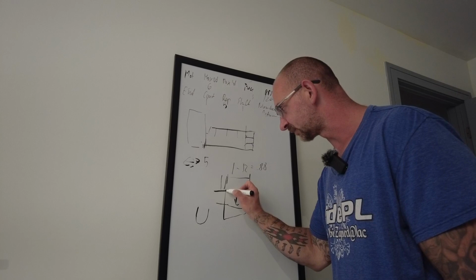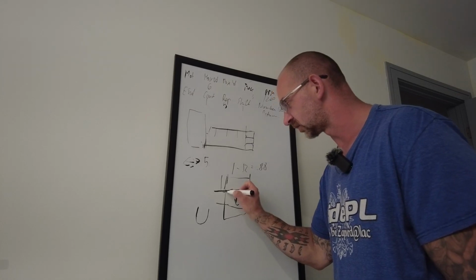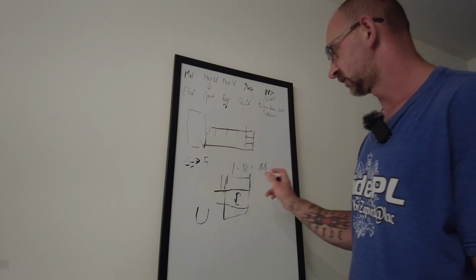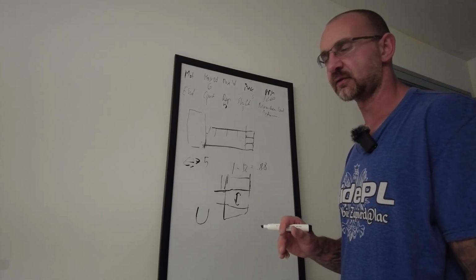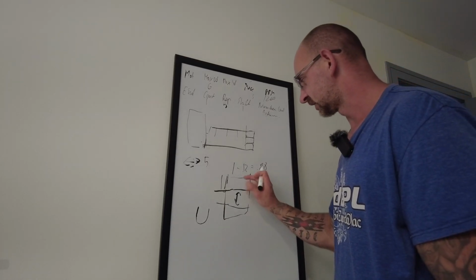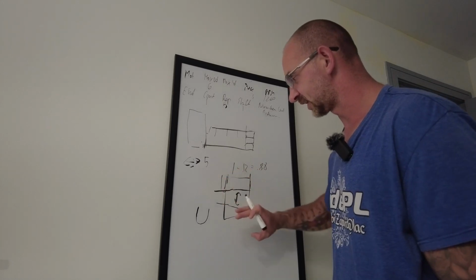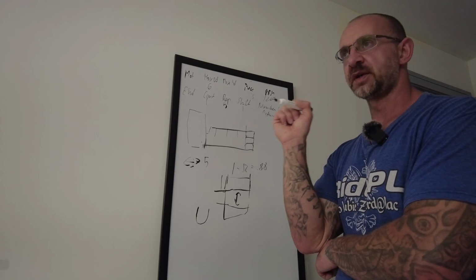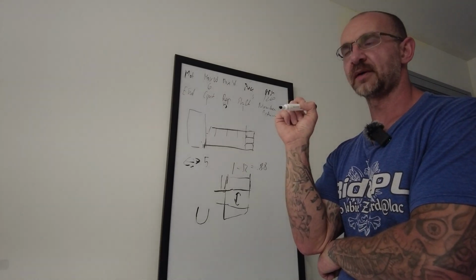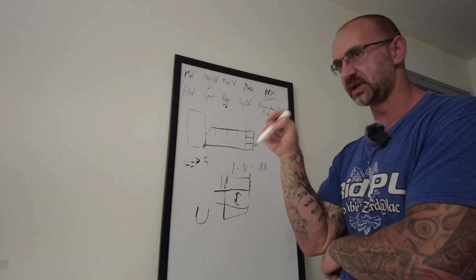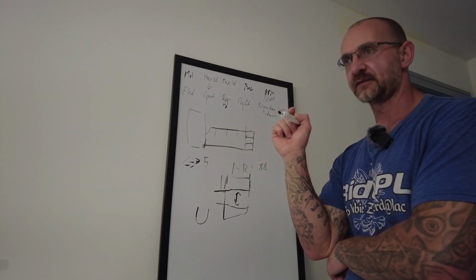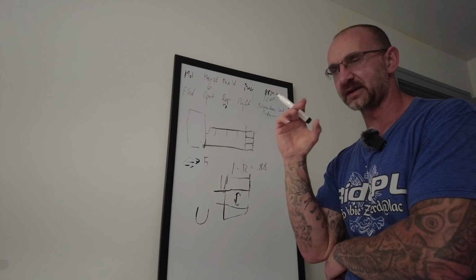So we'll push that material a little bit off, right? Because there's nothing holding it in. And then you can use a rubber mallet, and hit it where it's going to go inside and actually fall off. On average, if my ring is 1 inch, I can go about 10 or even 15 thousandths below that hole, and sometimes it might not even fall off, or it's going to be barely there.